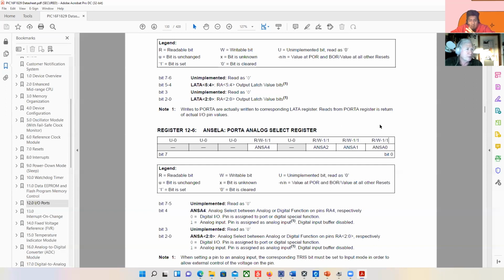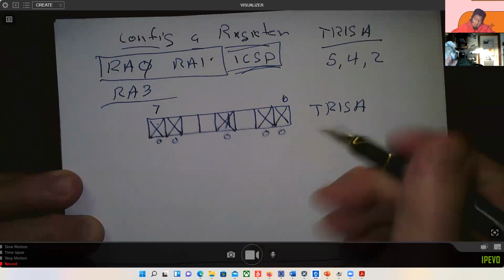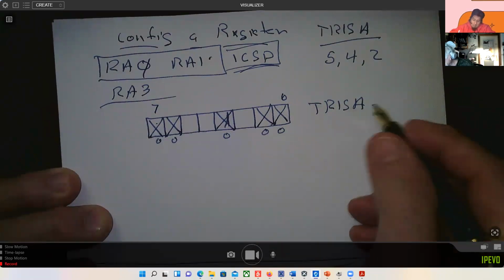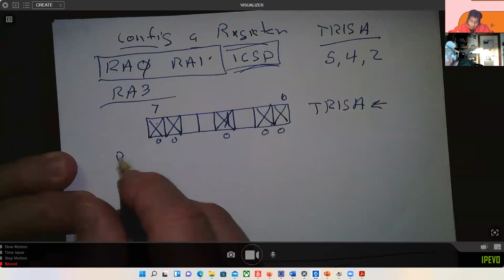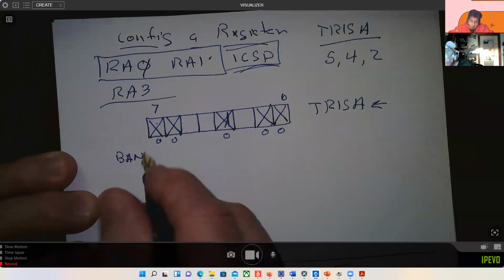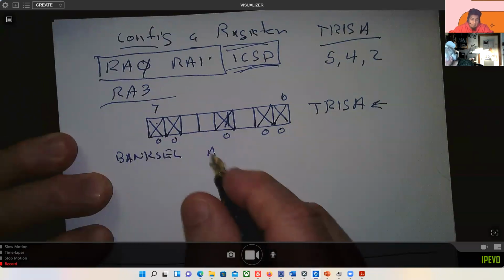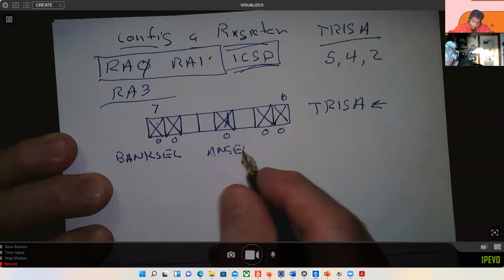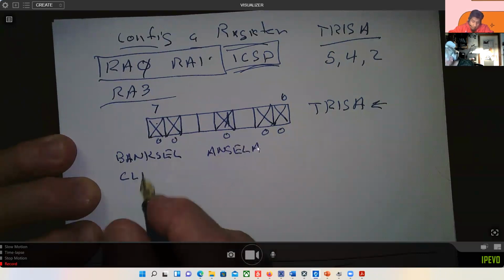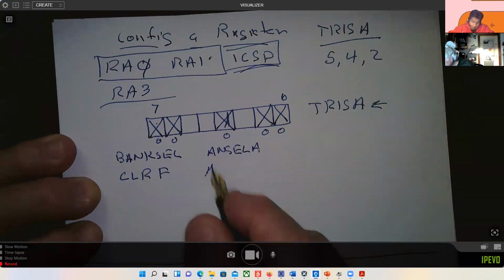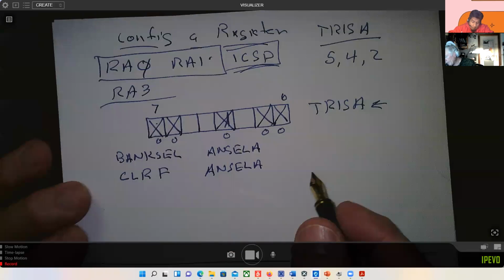And so let's see how we do that. I would just write, and then we're going to come back to the TRIS A in a minute. But the first thing I would do is BANKSEL ANSELA, and then I would just CLRF ANSELA.